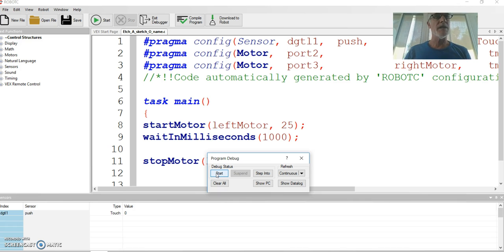So a forward movement of the left motor moved me from left to right, and I'm going to say it's about 2 inches. A good idea might be to actually get out a ruler and measure the line that it created. And then that's going to give you a proportional idea of how to create different size lines based on how long you run the motor for at a speed of 25. If you were to change the speed, you would want to test it all over again. I've been pretty happy with using the speed 25, so I think we'll use that for our first build. And that's it for this video.